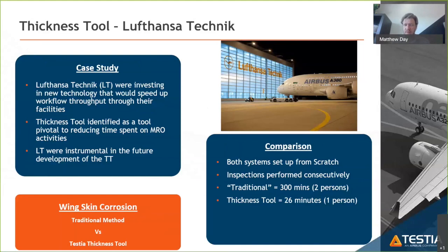In comparison with the thickness tool, it took one person 26 minutes from start to finish. That's switching the instrument on, performing the calibration, setting up the measurement lines at 45 millimeters apart, and scanning, and then generating the report after it.